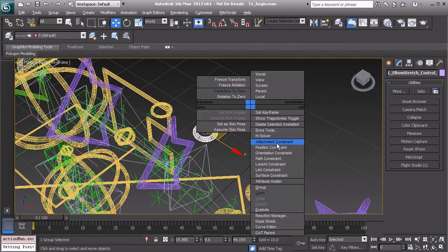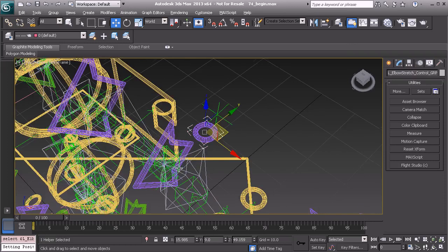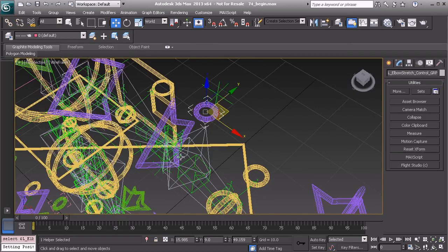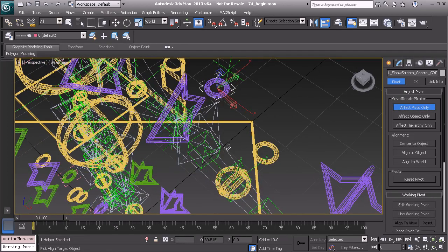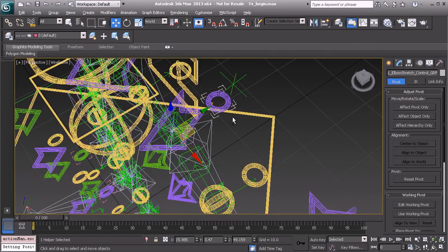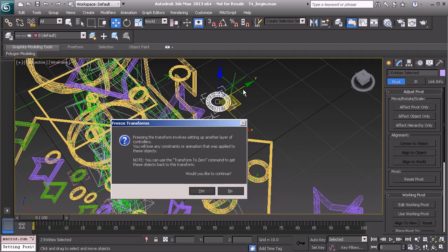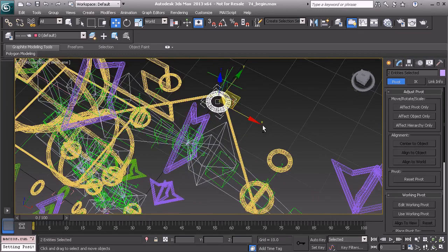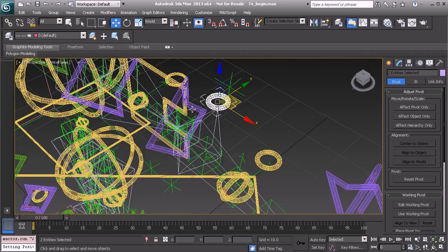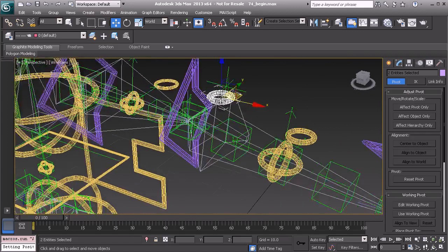Let's now open the group. We need to make sure that this group's pivot is right on top of the forearm as well. So let's take care of that. We'll head over to our hierarchy panel and quick align to the bone. From there, selecting both objects, let's freeze their transforms. Okay, once they're cleaned up, we now need to tie the z-axis of our forearm into the z-axis of our group. So let's find our expose node.